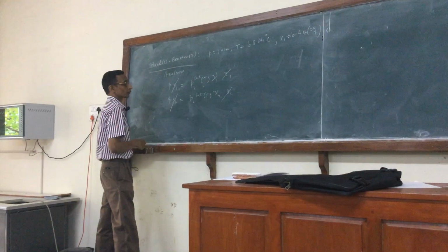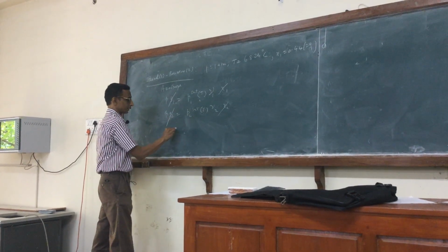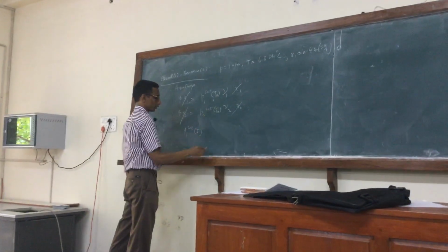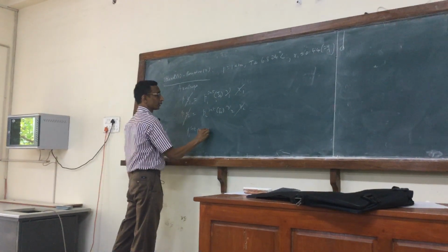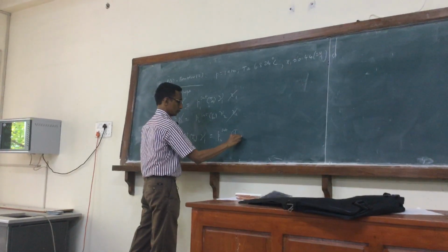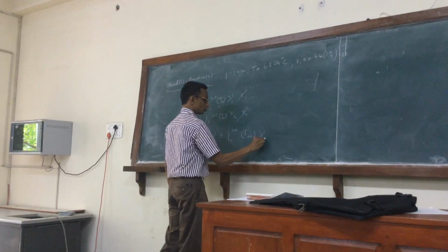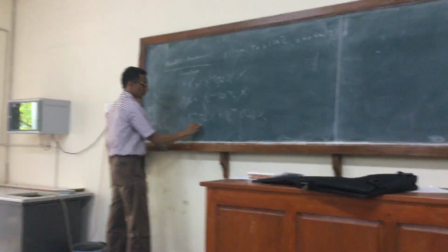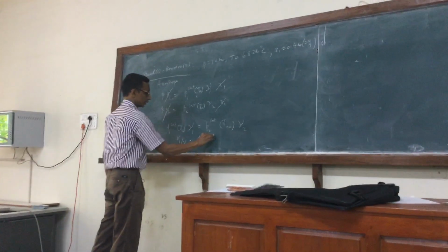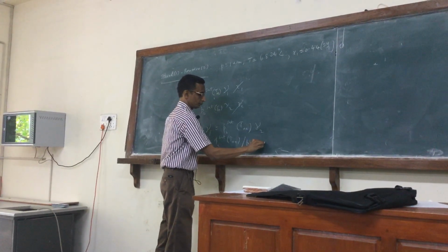And so, I have P equal to this and P equal to this. So I have P1sat, this is of course at the azeotropic temperature, that's very important to keep in mind, times gamma 1 equals P2sat times gamma 2. So what I get is actually a value for the ratio gamma 1 to gamma 2, which is P2sat at T azeotrope by P1sat at T azeotrope.